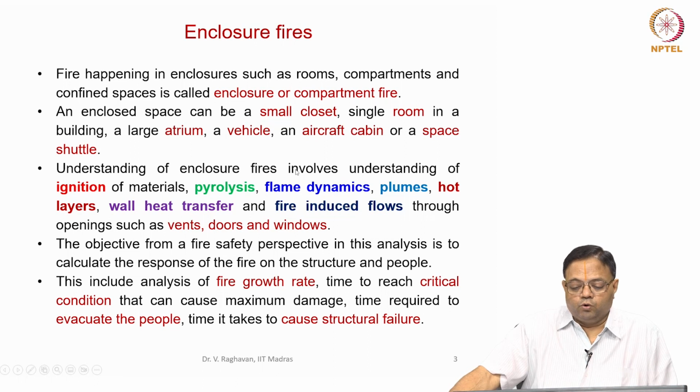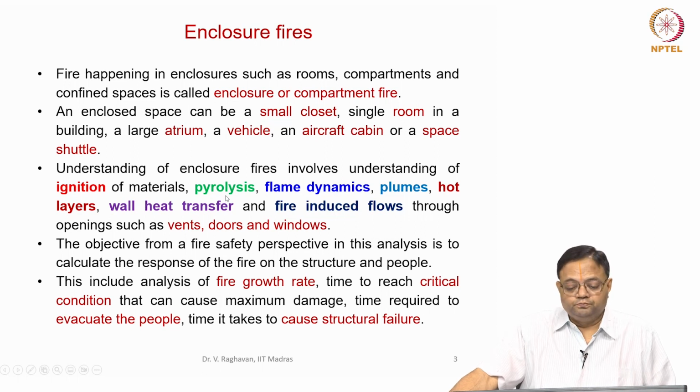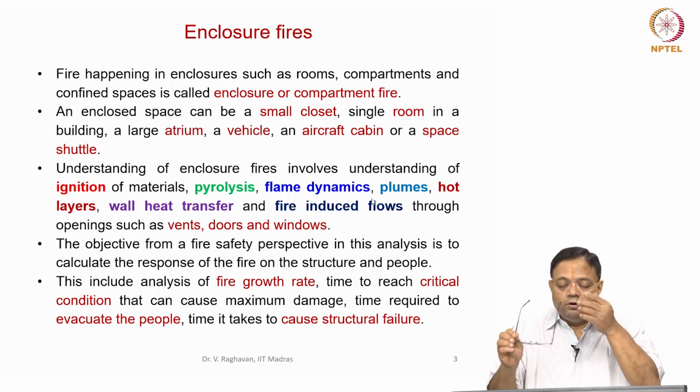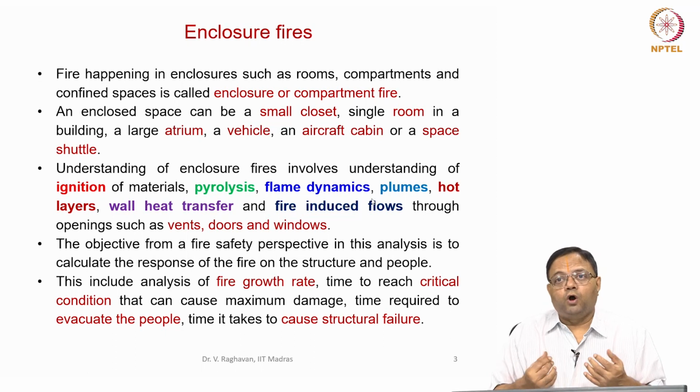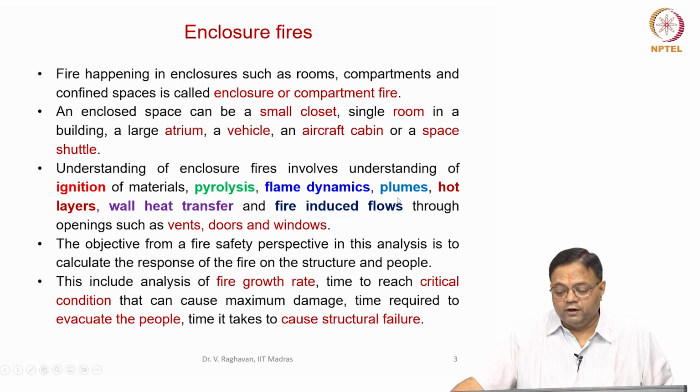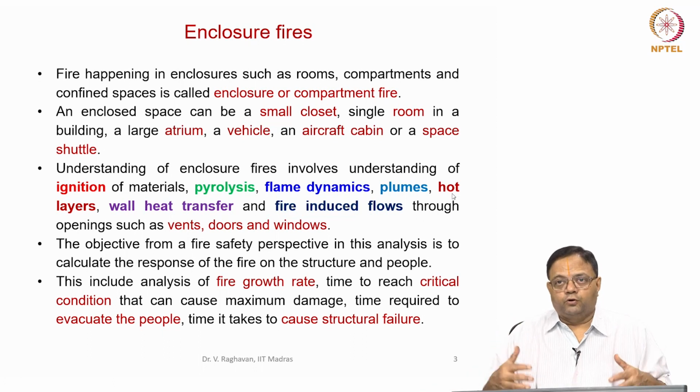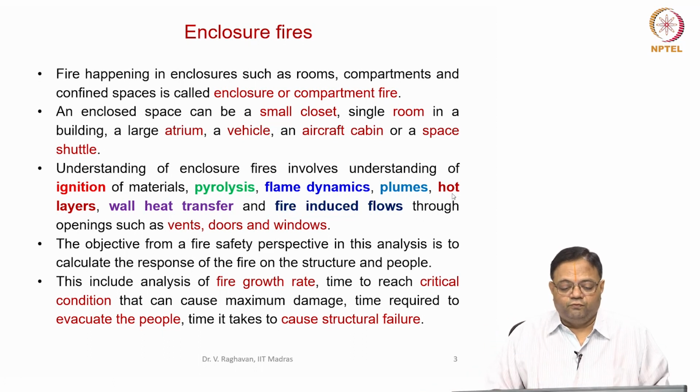Understanding enclosure fires requires a good knowledge of how ignition of materials occurs, then pyrolysis of solid and liquid fuels, then fire dynamics or flame dynamics, basically the rate at which the fire is growing. Then how the hot gases are propagating, plumes, ceiling jets are also included in this. Similarly, once the plume accumulates over the ceiling, the hot layers are formed.